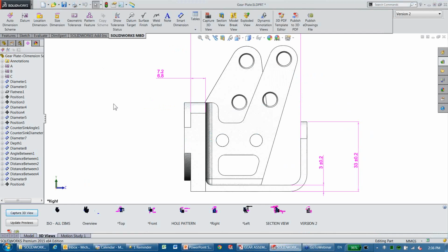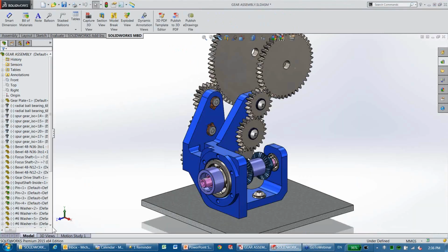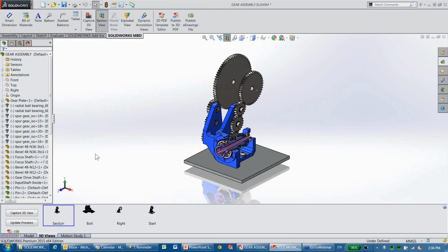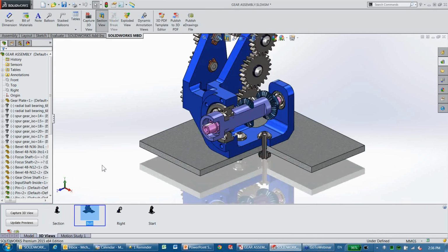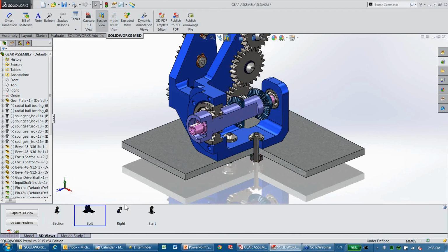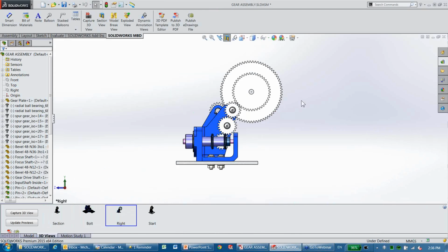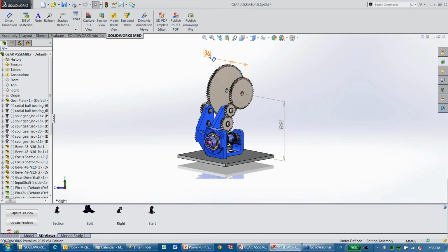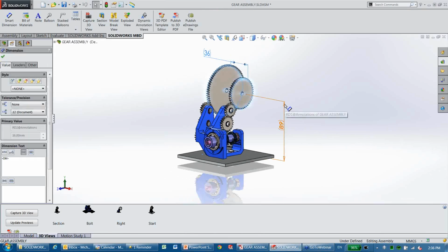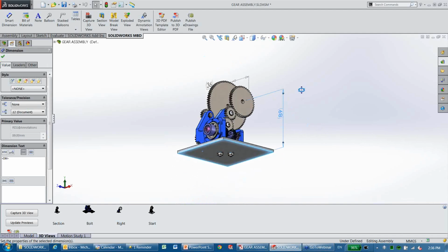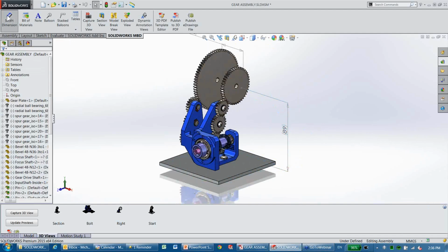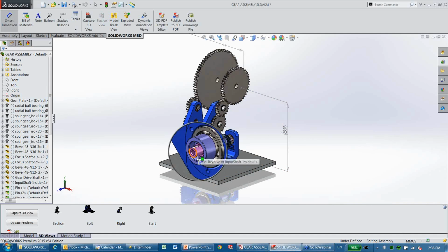Now, so far I've only talked about this single part, but what about assemblies? Well, pretty much like parts, you can create those views within the assembly. And here I got actually a couple of views showing sections. I got this view here that also have some dimensions to it. So if I select dimension, pretty much like I've shown before, you see the face highlight where these dimensions are attached to. But I can also add some more information.